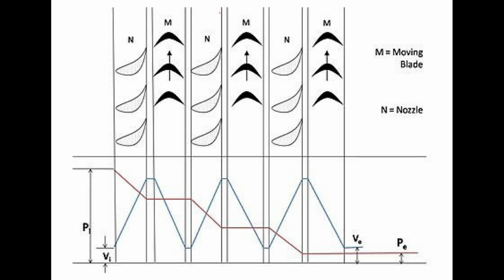When the velocity increases, the pressure drops at the initial stage, which means that as the steam flows into the nozzle, the velocity starts to increase as the pressure drops. But in the moving blade, the steam enters with a reduction of velocity at constant steam pressure.